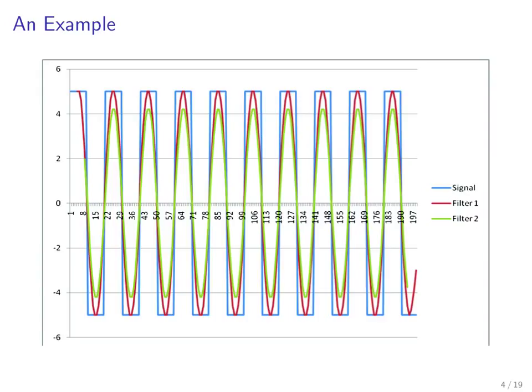And so by low-pass filtering, we have attenuated those edges, and we have also, in turn, reduced the signal's slope, right? With the blue input signal, we had an infinite slope. We had an instantaneous jump from 0 to 1, and then an instantaneous jump from 1 to -1, and so on. But we have reduced that slope substantially by low-pass filtering. Now we have these finite, lower slopes in the output signal.